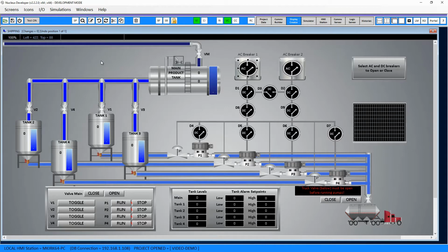There are 4 methods that can be used to send controls to remote devices. First, you can set control menus that will be presented when you click on an icon. Then you will define the control or controls to be sent when each specific menu is selected. So during runtime, if the operator selects this icon, the HMI station will display a dynamically sized window with the menus that you created. Each menu selection can send many controls if so designed.